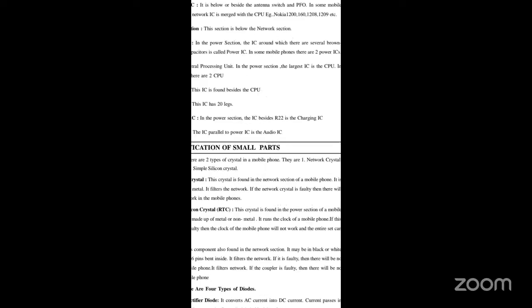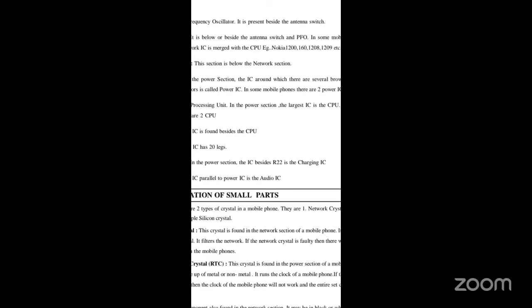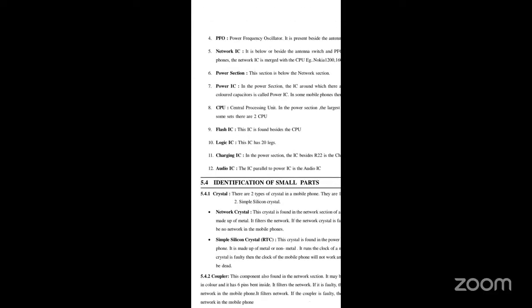Charging IC in the power section. The IC beside R22, sorry, R22 is the charging IC. Next one, audio IC. The IC parallel to the power IC is the audio IC. Next, identification of small parts.